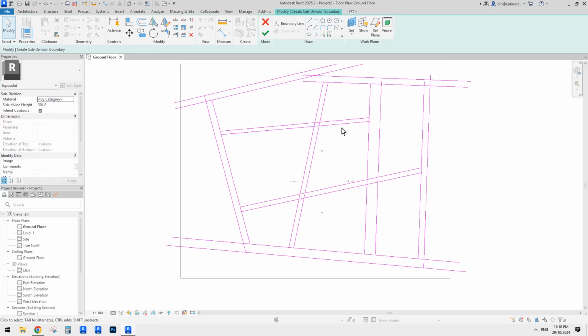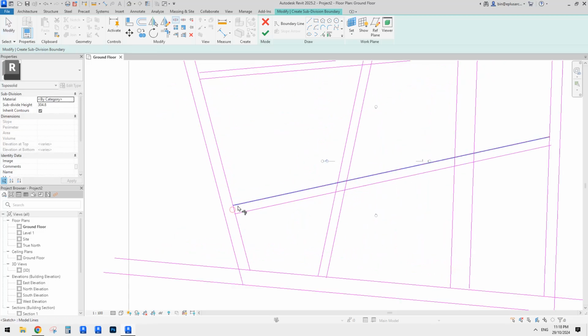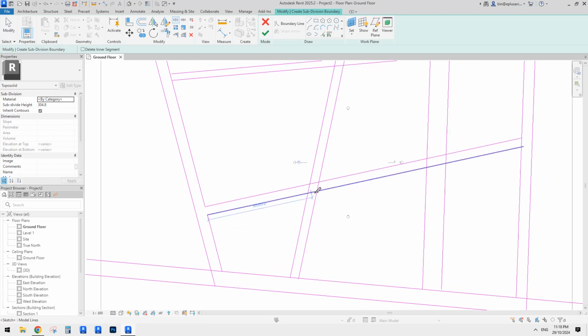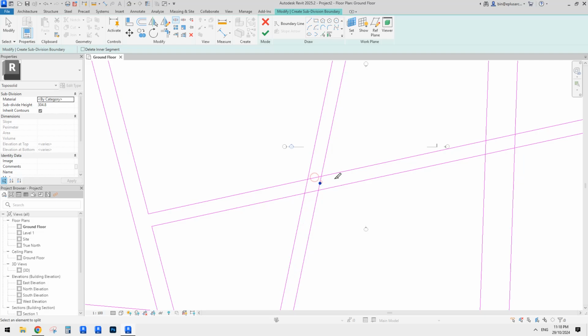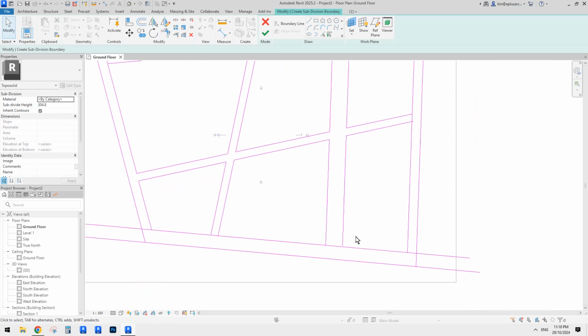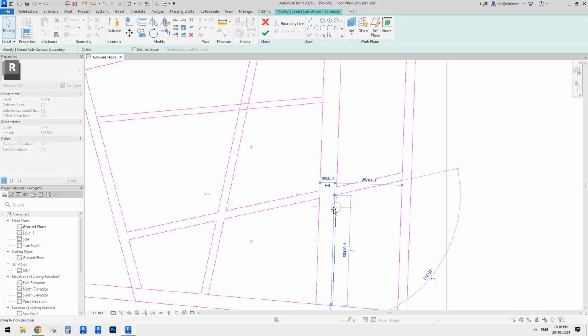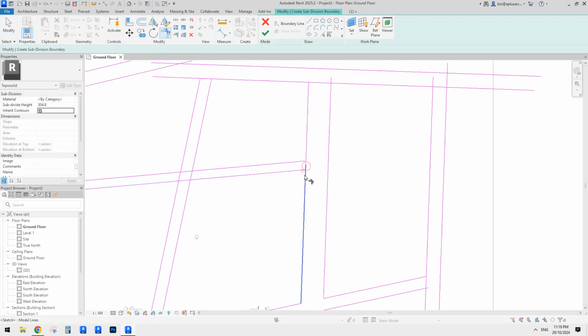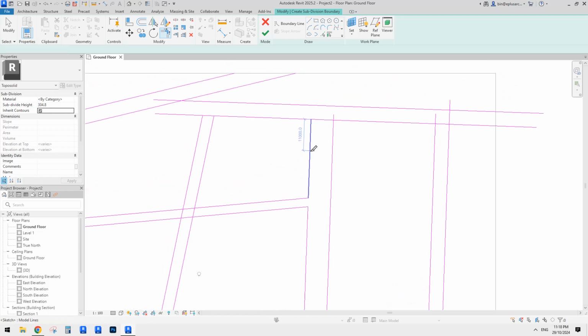Okay, now we need to trim them, right? First split, SL. For example, at this intersection, we can SL first, 1, 2, 3, 4, and trim, TR, and then we have something like this. You can still adjust them if you want to. Here SL, TR, SL, TR.